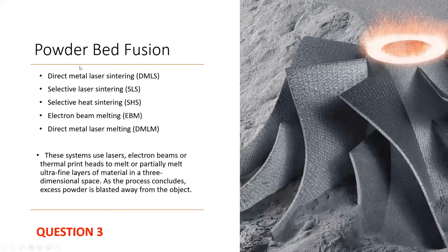Specifically as it relates to site furnishings, a lot of site furnishings are made of metal. So you can actually 3D print metal. It's a slightly different medium that you start with: metal dust. And then it's a slightly different filament head that you're using to build up the layers. Anytime you're working with a metal 3D printing application, you start with a powder bed of some type of metal, and then you're using some type of heat source, electron beam, lasers, all sorts of various heating methods, to slowly melt the dust layer by layer and build up your object. And I've got a short video on the next slide.